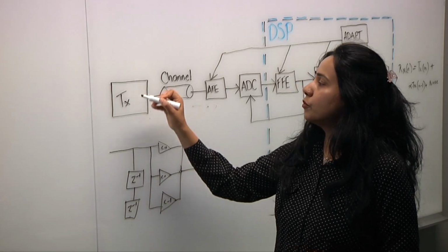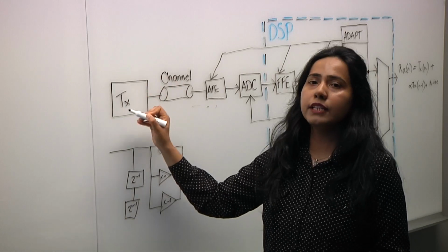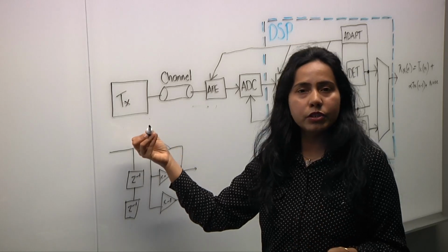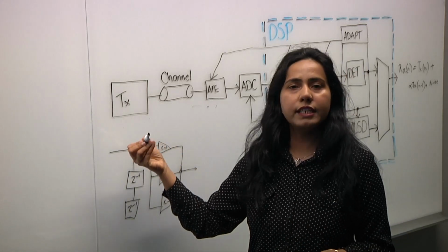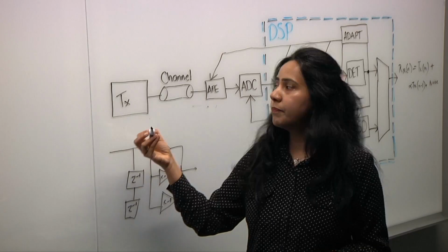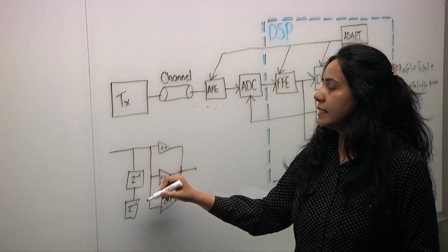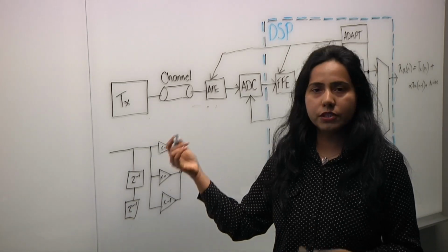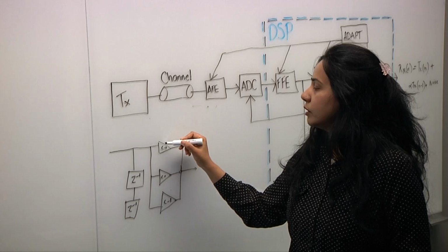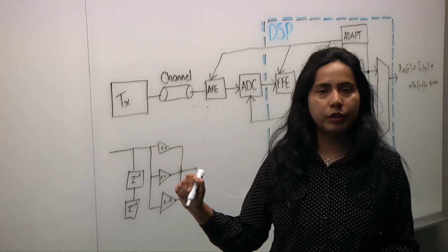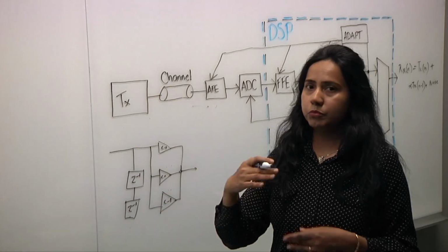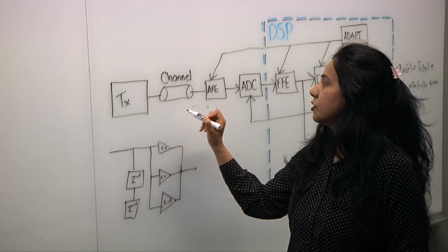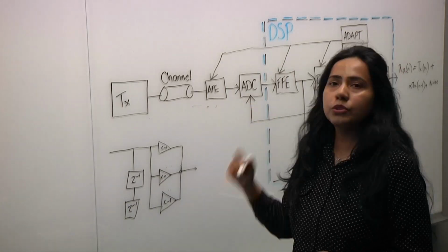On the transmit side, you would have one kind of equalization, which is your transmit FIR, finite impulse response circuit. It consists of several taps, and it operates in the discrete time domain, and you can optimize the value of these tap coefficients and boost the amplitude of the signal so that it has enough equalization to traverse through the channel and go to the other side.